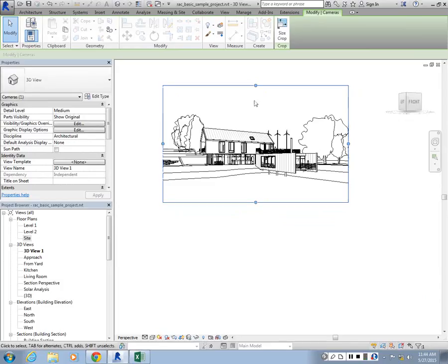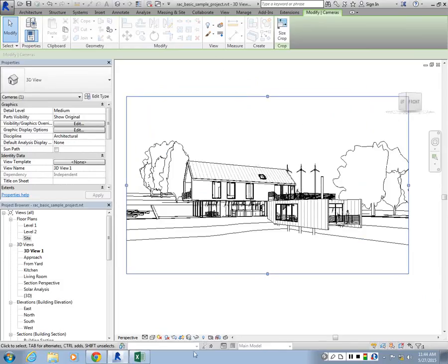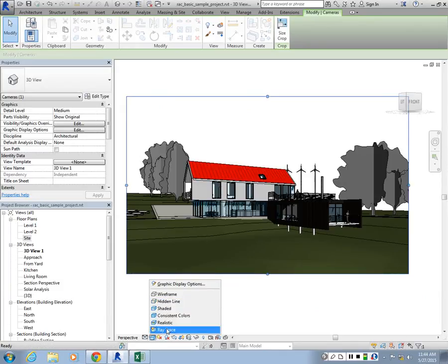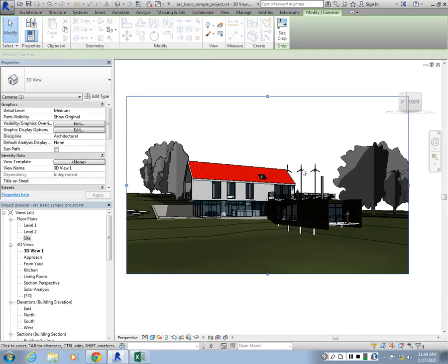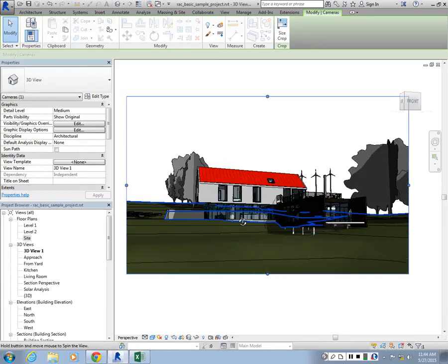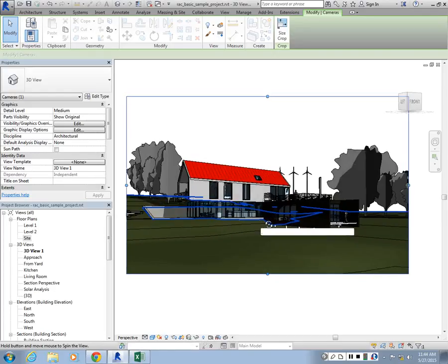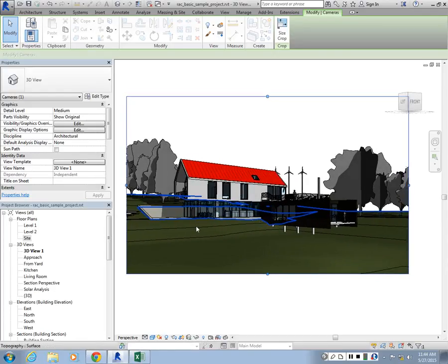And then everything else I did, like overriding visibility and graphics, choosing a shaded view or a hidden line view, enabling suns and shadows, like all this stuff you can also do in the new view we just created, which is this new camera I just included in the project. You have some overall controls here as well. By holding the shift on your keyboard and right clicking the mouse, you could orbit around the target a bit, so you can set up a better angle for the project, as well as you can also control this.